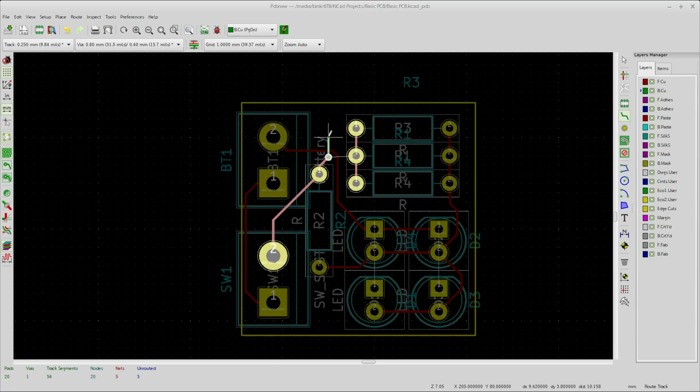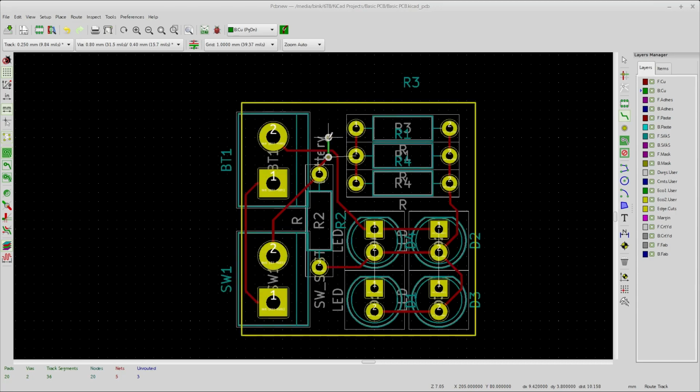And so then I can click over here, and I can bring this in. Now, this is a through-hole component. All this stuff is through-hole, so it doesn't matter if you connect from the top or the bottom. If you're doing surface mount components, which is what we're going to go to pretty directly after these first couple exercises, then you need to punch a hole. I'll show you. We need to punch a hole back through to the top, and now we lost our trace. That's weird.